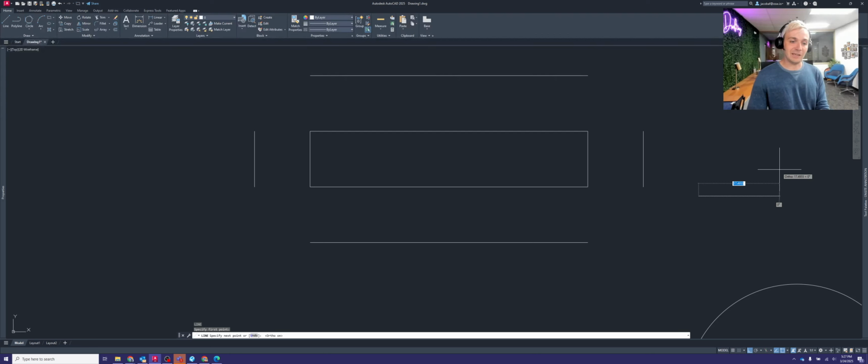If you hit F8 or you hit this button again, it's going to allow you to use whatever angle you'd like. It doesn't matter if it's 90 degrees or not. But if you have F8 turned on, it locks to 90-degree increments, which is really nice for some things. I'm always turning that off and on as I'm working in AutoCAD.